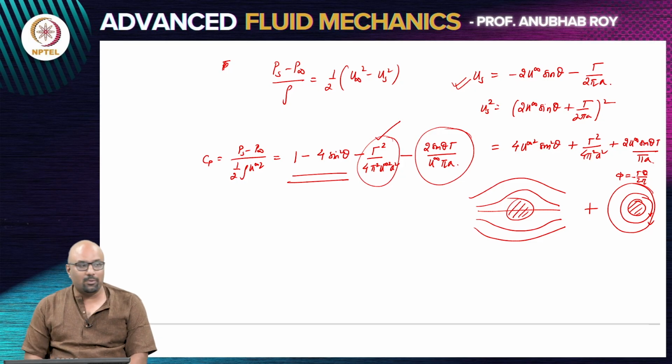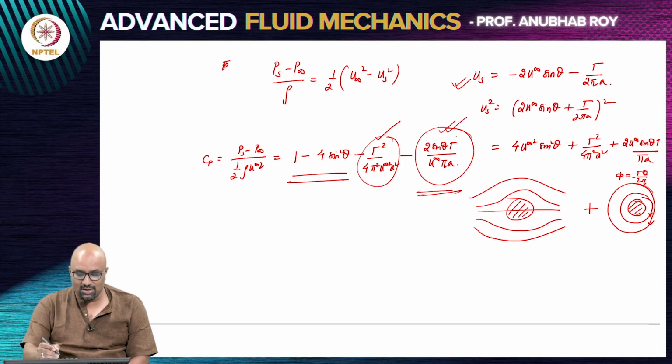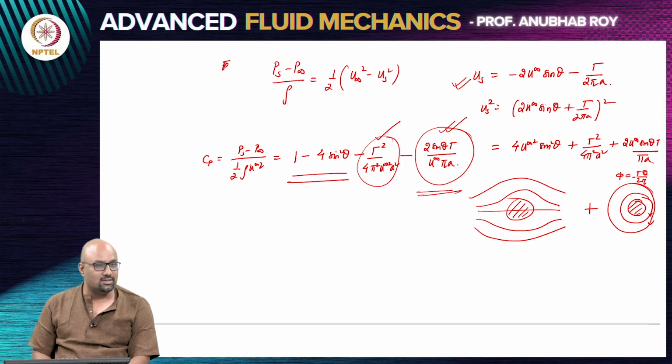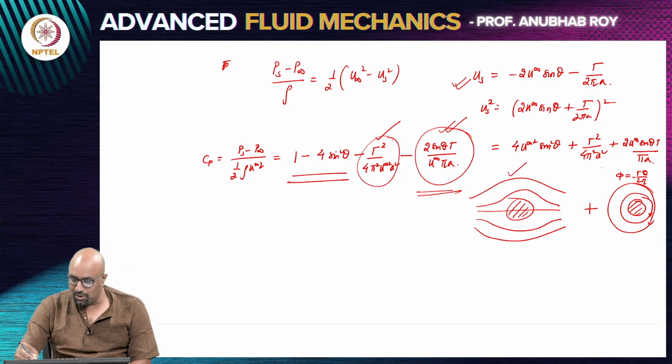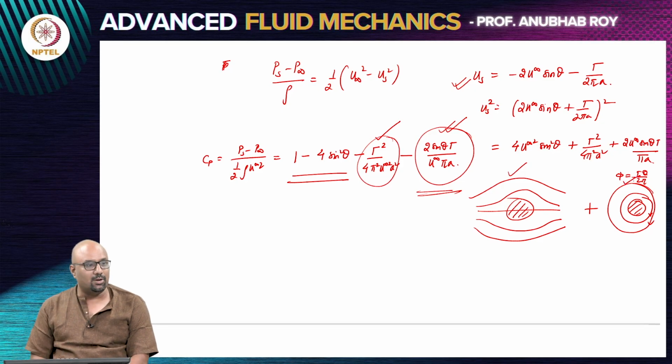The combined problem, when you actually compute, is basically breaking this, and the pressure Cp that you have here in the combined problem reflects this asymmetry, because pressure is a quadratic function of your surface velocity, right? The pressure from this problem plus pressure of this particular problem is not the pressure of the combined problem.